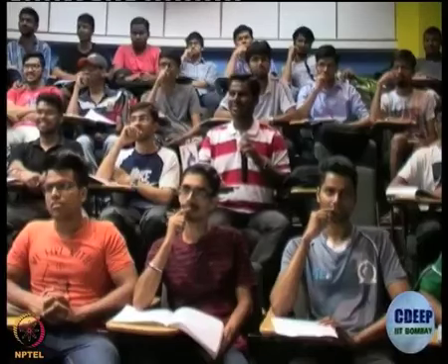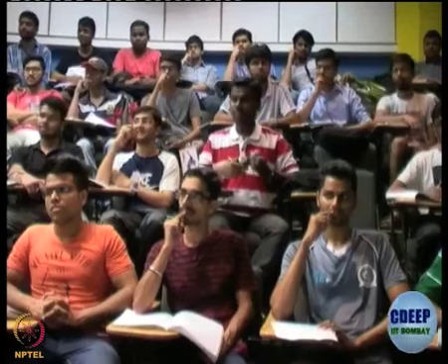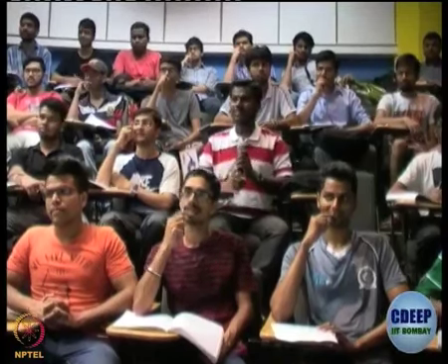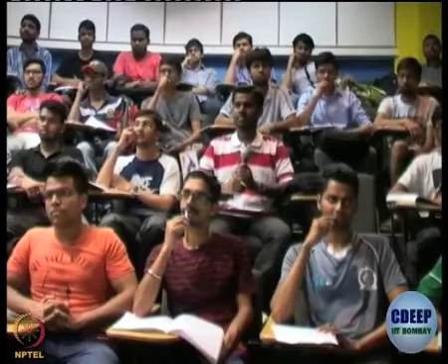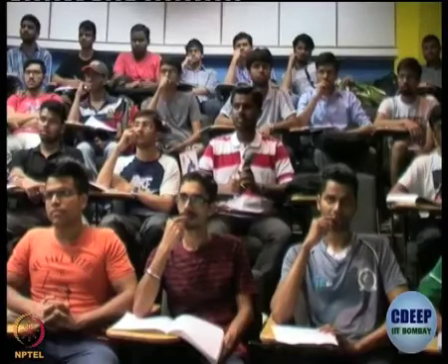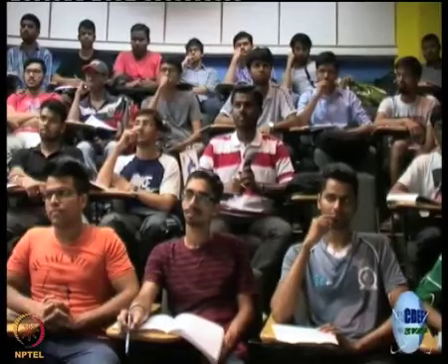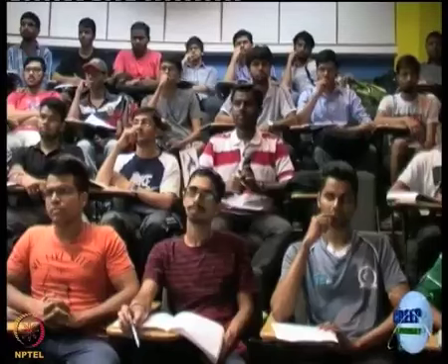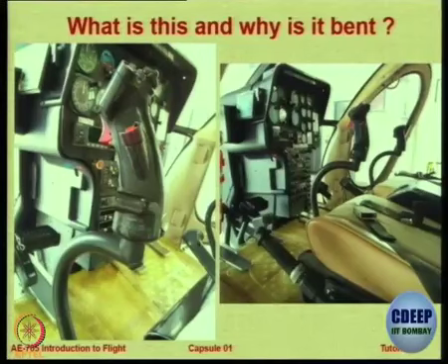The pilot is also a driver anyway, so you are not technically wrong, but we call the driver of an aircraft a pilot. So yes, this is to clear the knees of the pilot because there is a situation of very cramped operation in the helicopter, and this is the helicopter yoke which is used for giving the command, except one on the bottom. You can see on the right picture there is a shaft-like thing on the bottom that is meant for the collective pitch. I'll talk about this when I talk about helicopters.